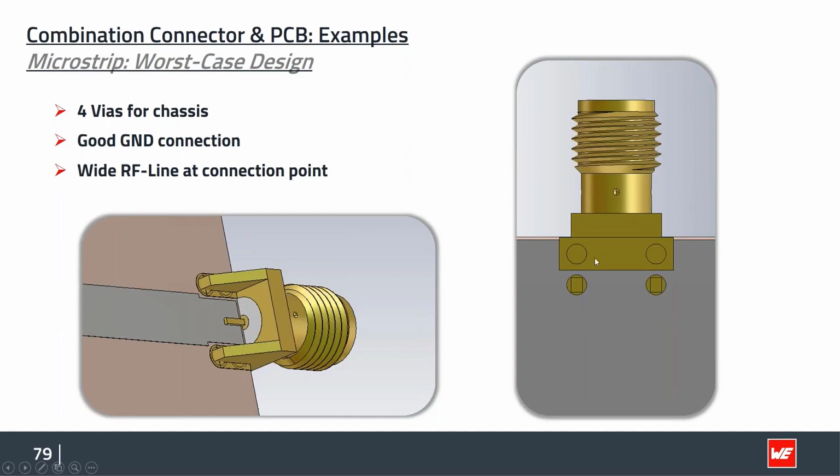On the bottom side, we create a pad on the ground to the ground layer and close it with solder, so to have the connection to the housing and to close this slot antenna we recognized in the first simulation. And now we have a good ground connection, a really good ground connection, and we see what it will do.